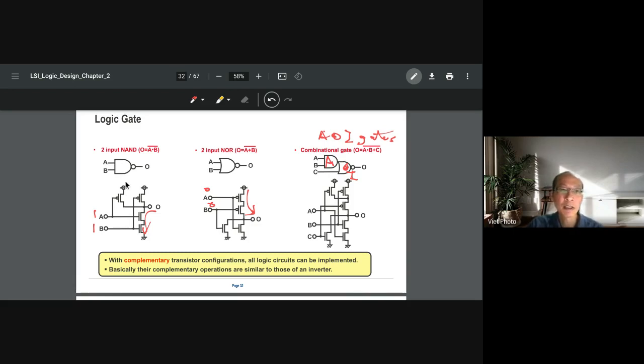This one is simple. You have a NAND here, so that means a NAND2, right? The NAND turns on only when the two inputs have a high value. So here you have a 1 and 1, and both of them turn on, which is like a short here. This one will be tied to 0, so 1 and 1 gives an output of 0.